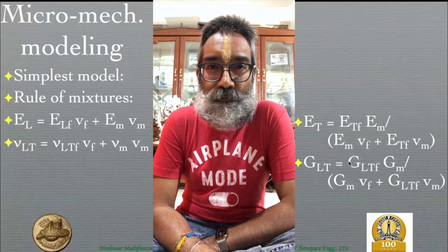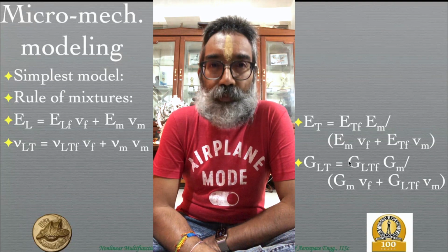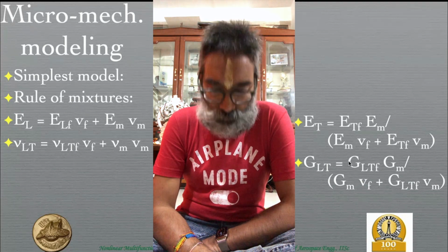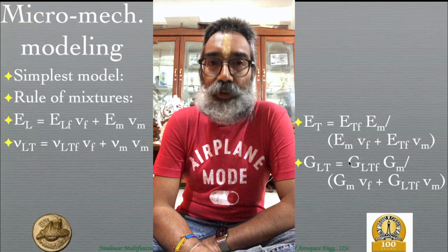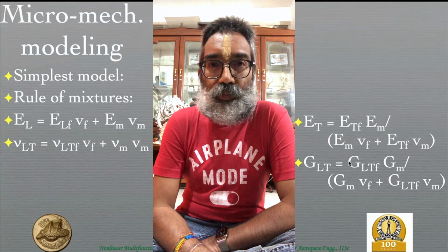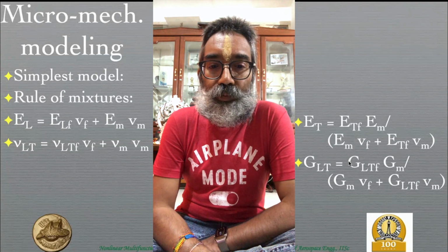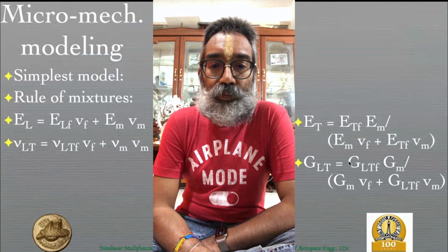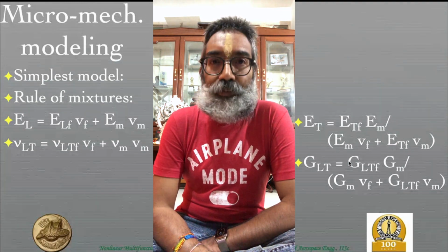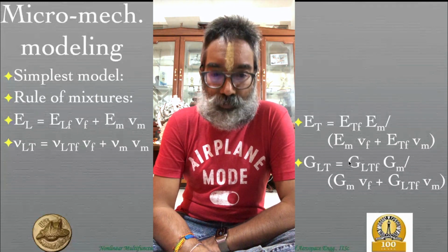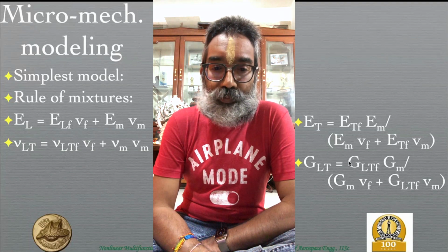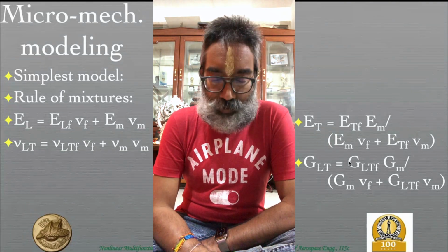I just had one doubt. Whenever we talk about the shear stresses, or basically the shear strain, we talk about the angular change in angle between two perpendicular lines. Correct. How this 90 degrees changes to 90 plus theta or 90 minus theta. Correct. That theta is actually the strain. Right. So why cannot we talk about two other lines which are not perpendicular to each other in the material? That can also happen, like say we don't have a rectangular cross section but some skewed cross section. There the edges are not perpendicular, right? So why don't we talk about those things?